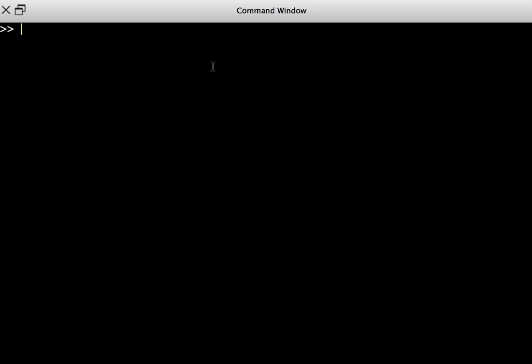Here it is. I just use a function called fplot, and then I'll give these three functions. fplot is an inbuilt function in MATLAB, and in fact I am using Octave software, which is the open source version of MATLAB. So 10 into sine of 314t. Instead of t, I have to use the variable x, because that is what the fplot function takes as the variable. So 10 sine 314 into x. This is the first voltage.